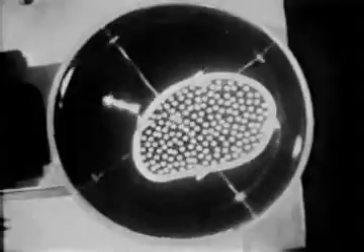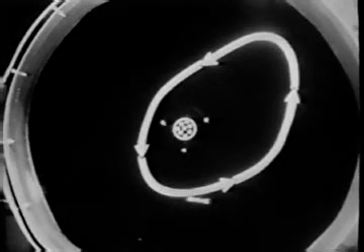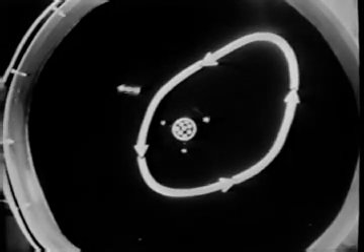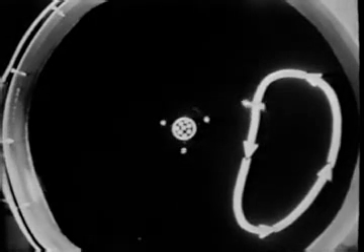In the spiral vortex tank, the flow is non-vortical, except for the concentrated vortex core, which accounts, so to speak, for the whole motion. All fluid circuits surrounding the core have the same circulation because they contain the entire vorticity flux. All fluid circuits not surrounding the core have zero circulation because they contain no vorticity flux.